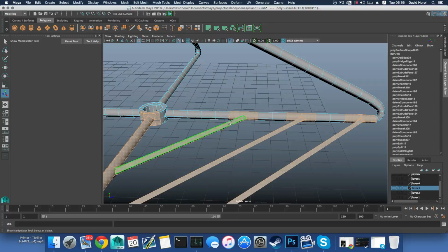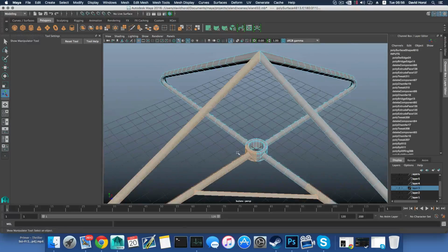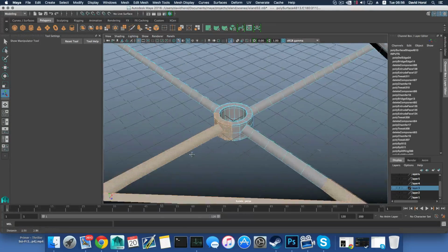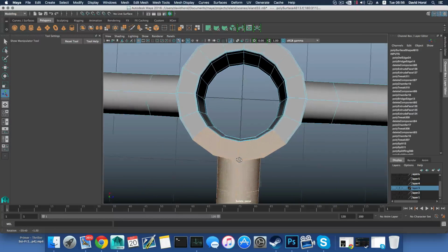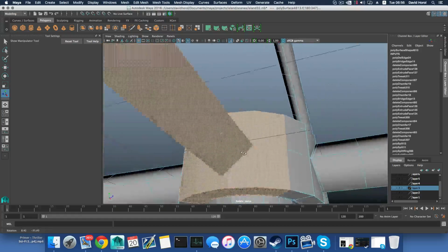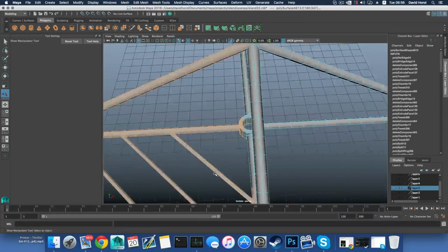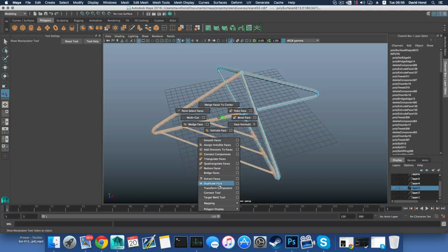That way, whenever you cross some that are already selected, they won't be unselected. Everything here is selected, and here is what's important. So Control Shift and make sure that everything that belongs to these 4 sections has been selected. Okay? And we will do a test here. Maybe I got it wrong, but we shall see. Well, let's see, shift right click, duplicate face.